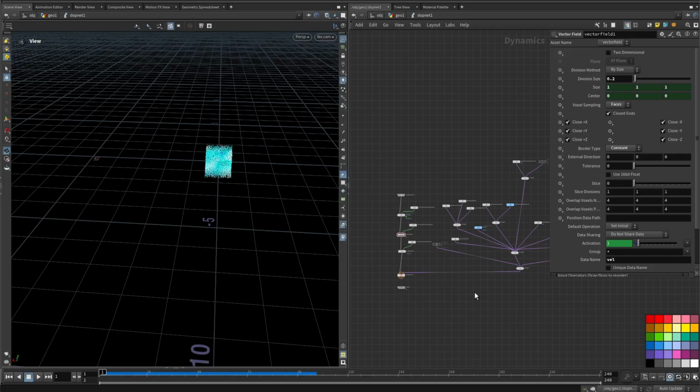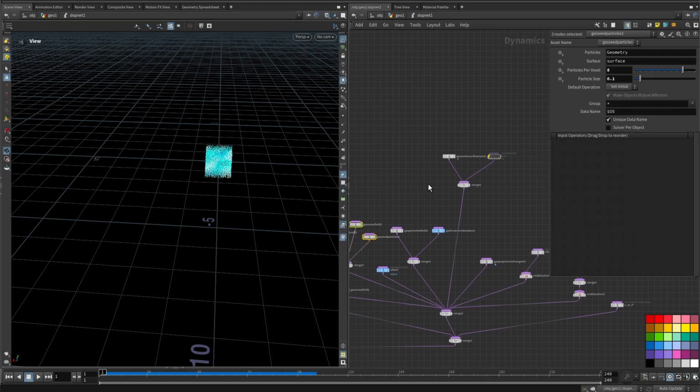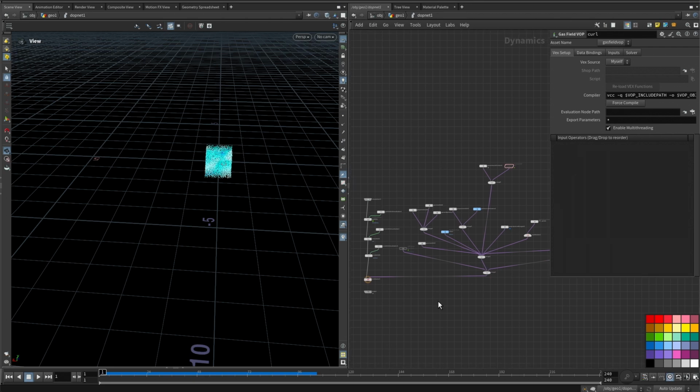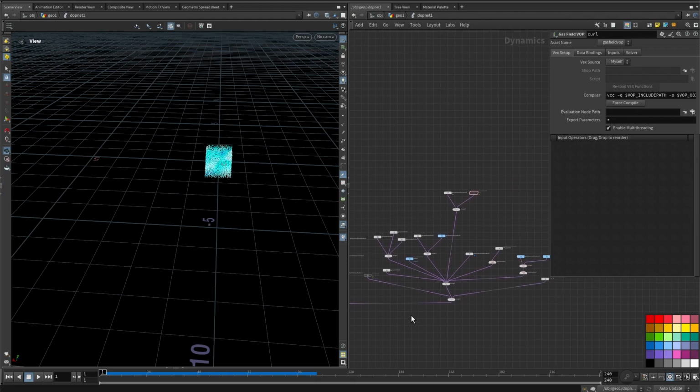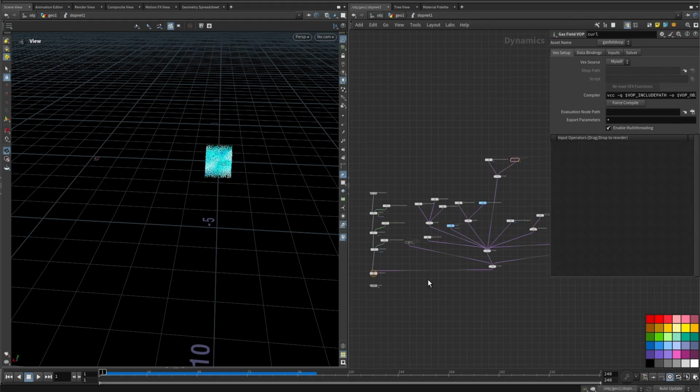So you're getting the idea of how to create solvers in Houdini, or creating a fluid solver in Houdini. Again, it's rarely that you need to create this from scratch, but you might find yourself adding some of these microsolvers to the existing flip solver. That's very common, and you'll see that a lot in bigger productions. But yeah, that's it. That's how a flip solver works, and that's the anatomy of a flip solver in Houdini.